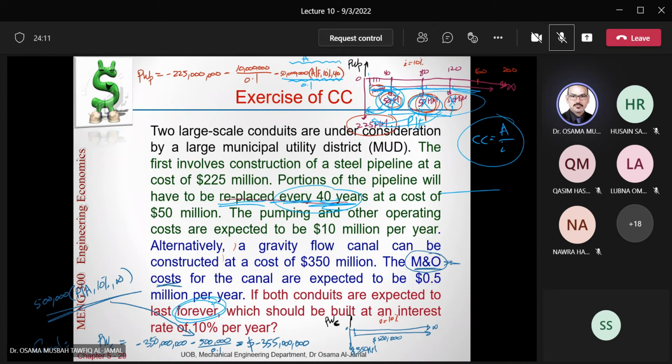I'm not going to go deeply inside the engine to change some of the seals. And that will be every 100,000. Theoretically, they said every 100,000, which is every 5 years. So in every 5 years, you need to do a major shutdown or an overhaul.